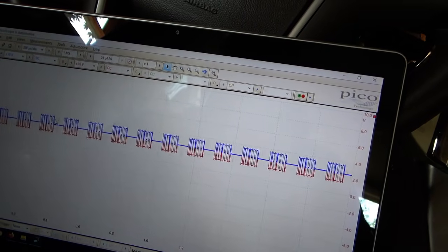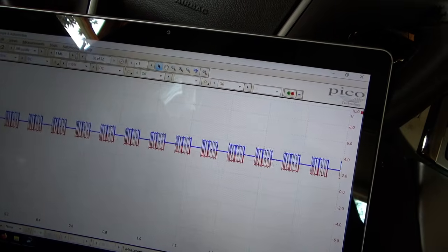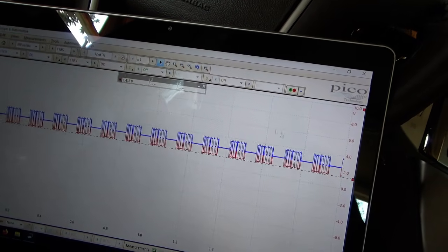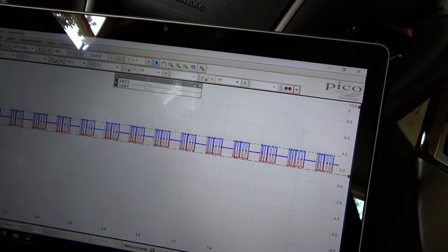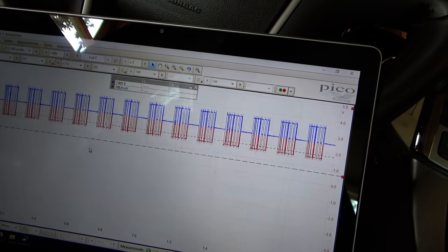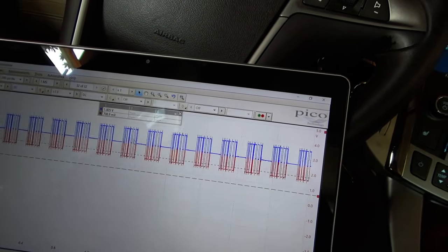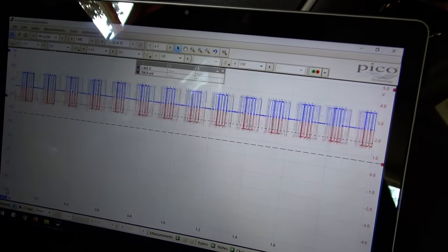So this tells me nothing's wrong with the wiring or the voltages. As you can see, about 1.5, and this one goes up to 3.5, the bias is 2.5. I mean, that's great. We can even decrease the voltage scale. Everything looks great. But the pattern is something's just talking, can't communicate.